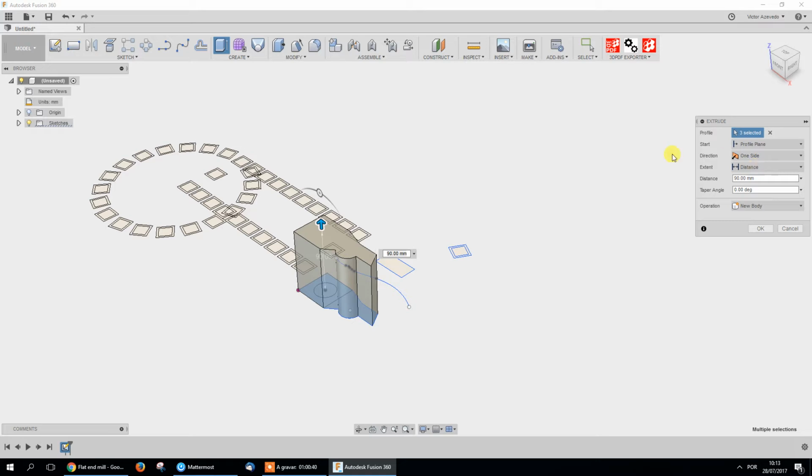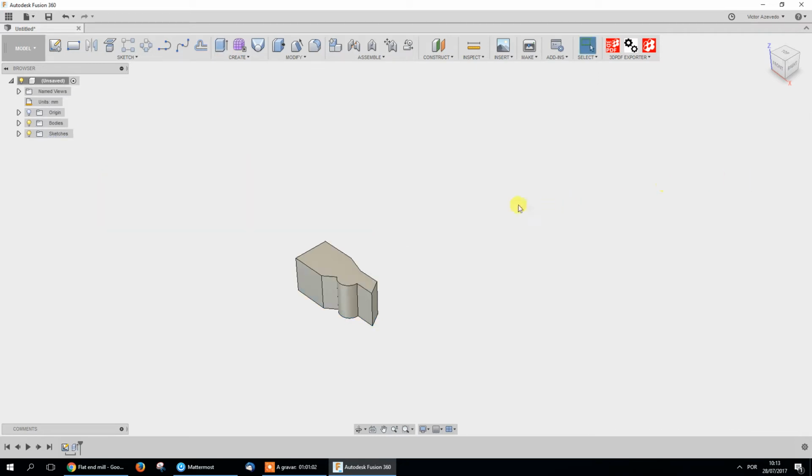So, if you have two extrusions, you can make a third one from one to the other. That's why we use to object or all. In this case is the first one. Let's leave it distance. You can also put the distance here. Let's place 50 and enter. It will close the sketch.